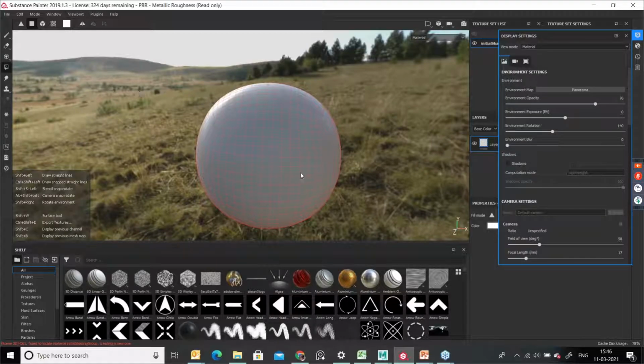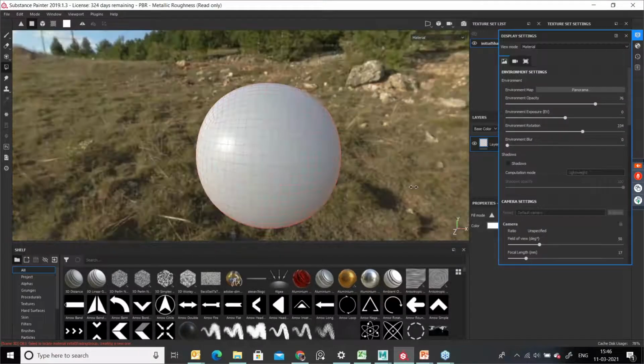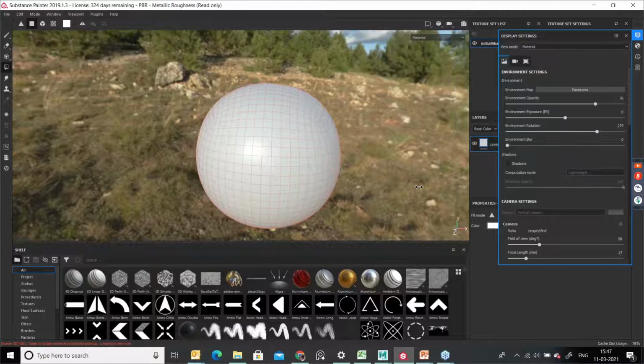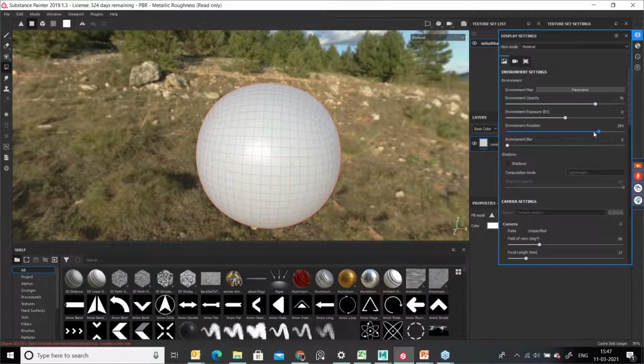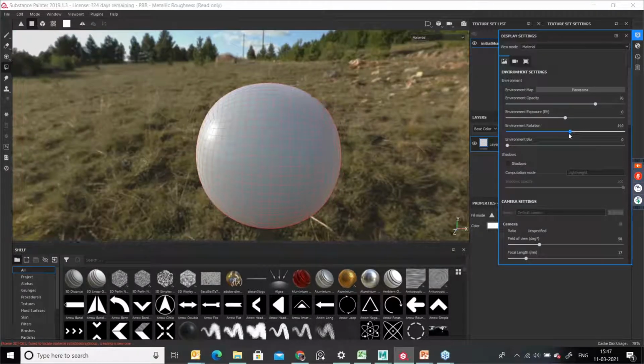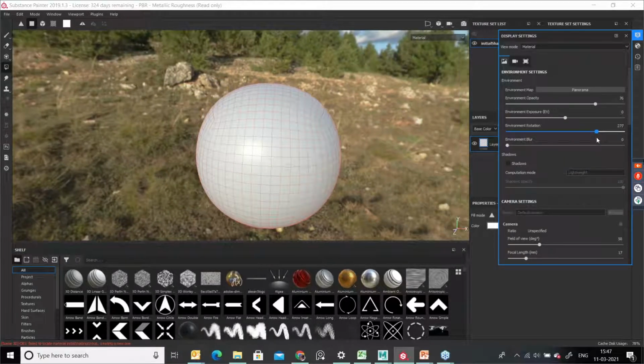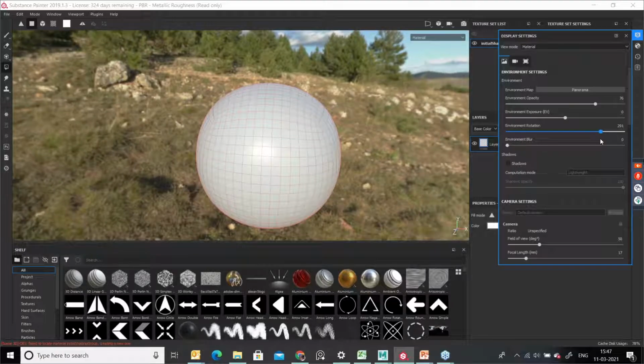You want to bring the sunlight to the front and see the model clearly. You can rotate this environment with the help of Shift and right mouse button. Otherwise, you can use this slider manually to bring the light exactly to the position. So is it clear? I think you got the idea about environment settings now.